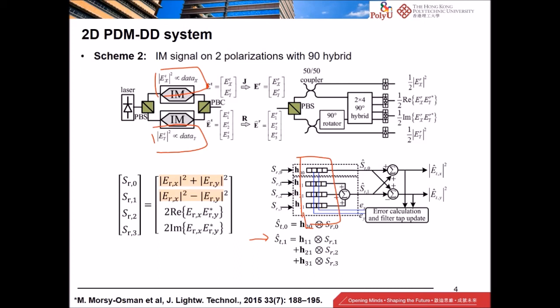So that will be more complicated than the case to recover ST0. Once you have obtained an estimate of the first 2 entries of the transmitted Stokes vector, the original signal amplitude from both polarizations can be estimated easily.